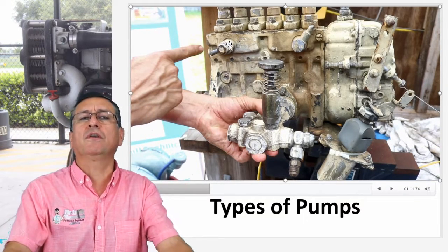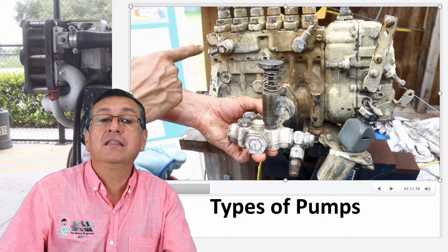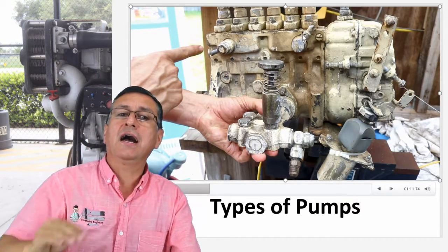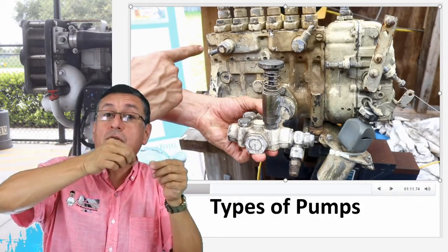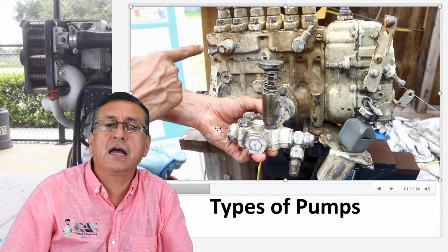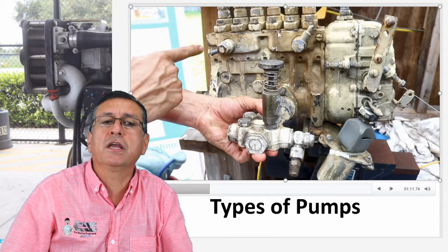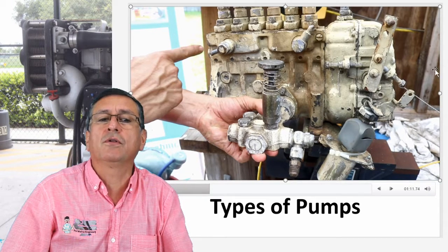Okay, the fuel enters here, and after that enters the fuel injection pump. This is the input of the fuel injection pump. Internally, in this mini engine, you have a small manifold for intake, and on the other side, in the back, you have another manifold inside of the mini block for the return. Okay, look at this. The fuel enters here, passes over there, and enters here. That's the input, and the fuel enters each plunger, each small cylinder. And on the other side, the fuel returns, and this is the return that goes into the fuel tank.